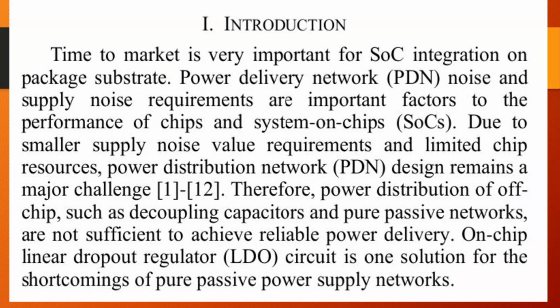Therefore, power distribution components such as decoupling capacitors and pure passive networks are not sufficient to achieve reliable power delivery. The on-chip linear dropout regulator circuit is one solution for the shortcomings of pure passive power supply networks.